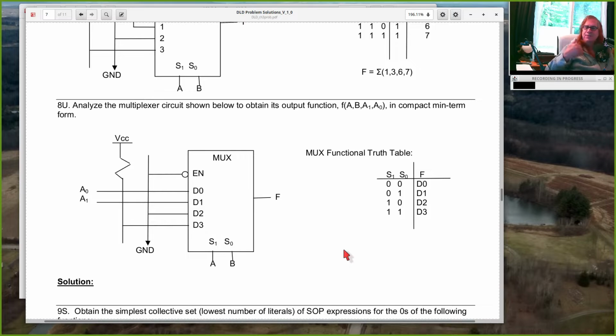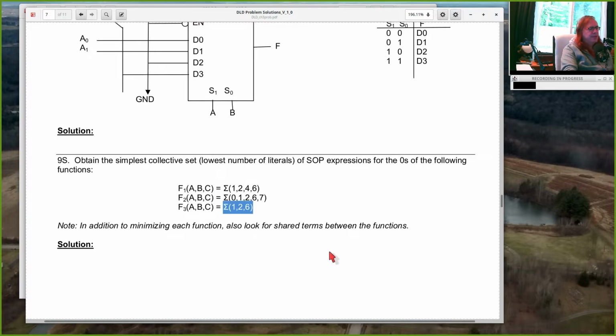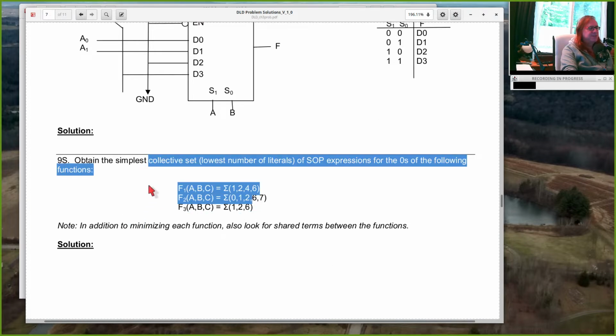First we looked at truth tables and understood what they did, and then we moved on to saying, okay, so I want to build a circuit that controls a traffic light, right? What should the circuit look like? How do I build it? And so that's the system diagram, the truth table, the equations, the simplification, the circuit, and so on and so forth. So we're going to keep going between these 2 levels. And so this is more of kind of the synthesis skill set.